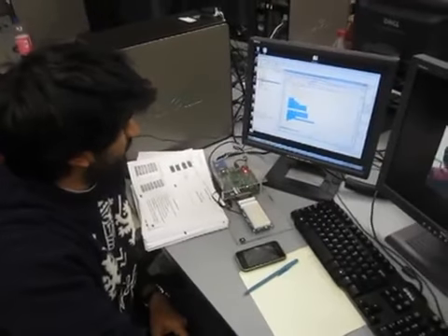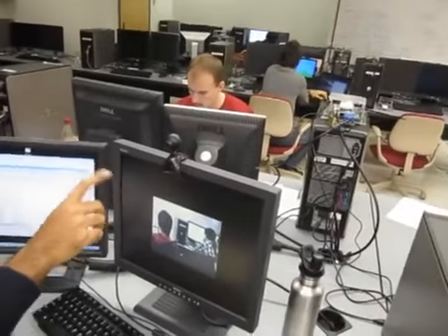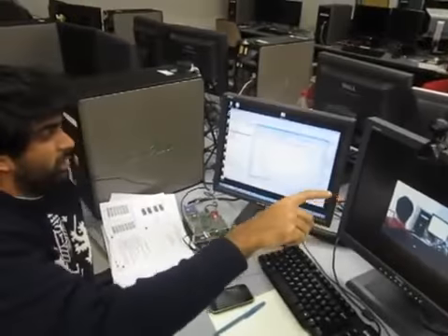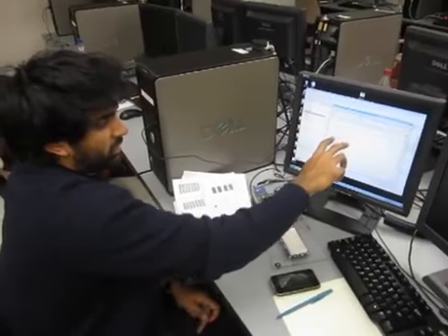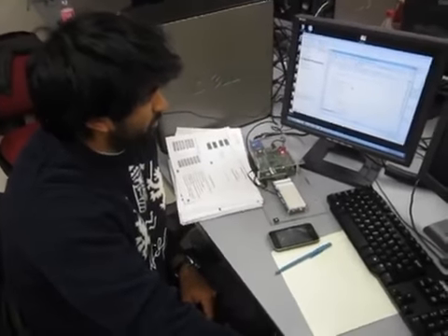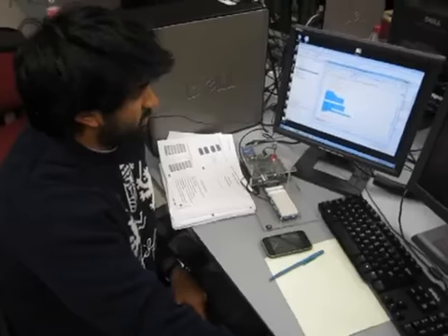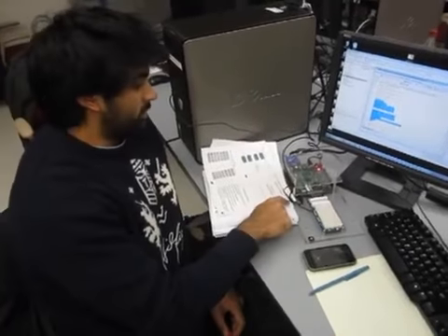And the second script takes the 256 RGB video, gets the current snapshot of it, and downsizes the video into 8-bit color using these simple bit shift operations. From there, we serialize the data and send it over UART to the FPGA board.